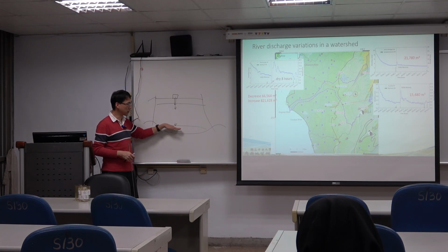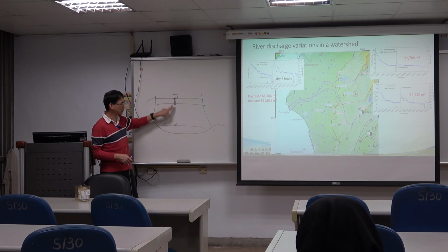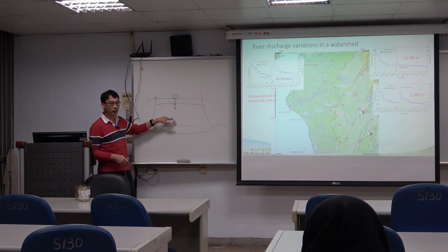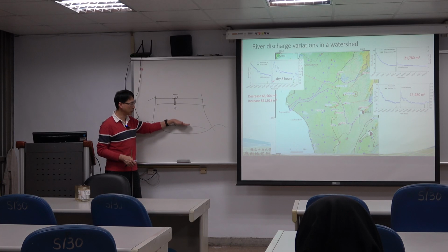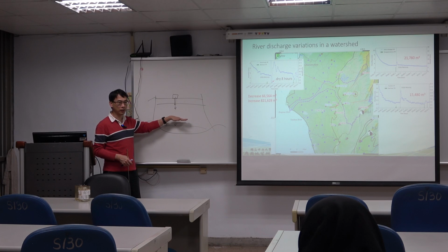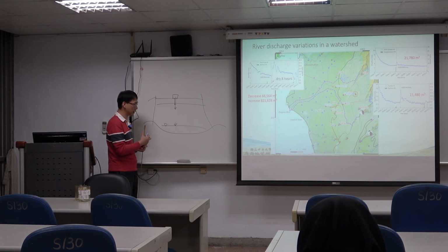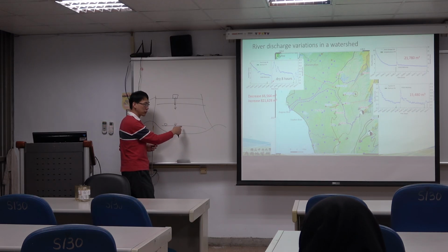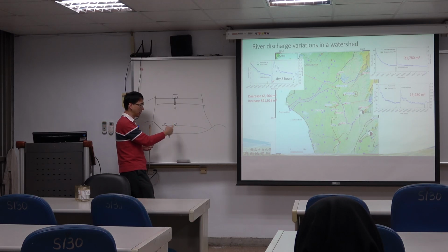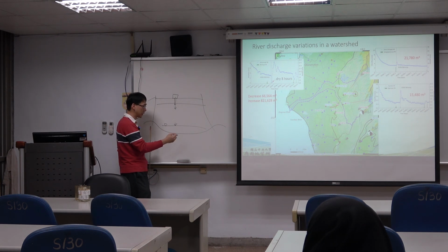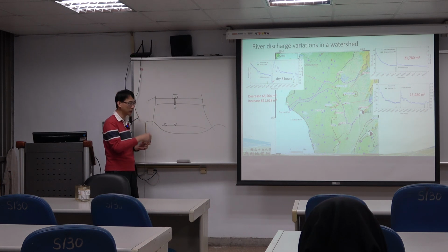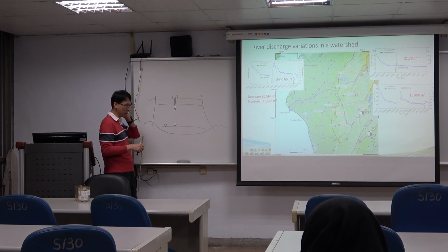So when your river surface increases or decreases, they use this kind of traveling time to invert the level increase or decrease. And after that, they use that to calculate the discharge quantities. That means they're using the elevation to calculate the discharge, and they assume this one is constant. So commonly they need to do corrections. There will be a regression curve to do the corrections.